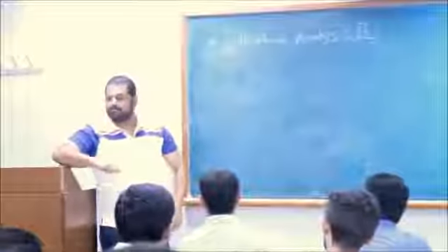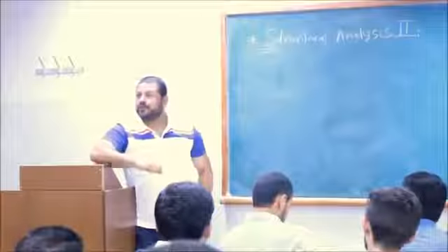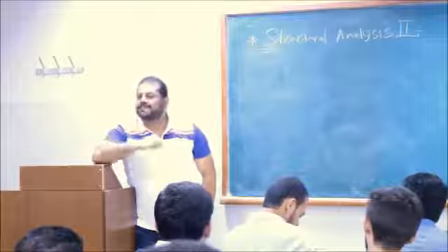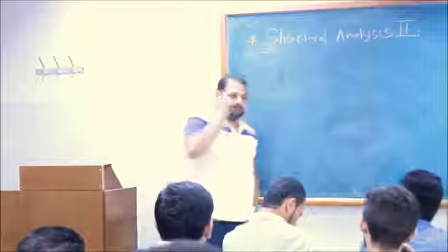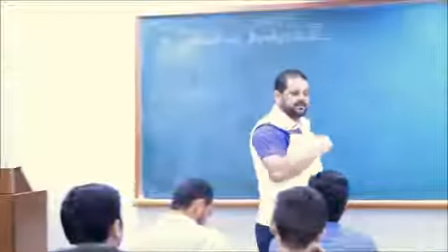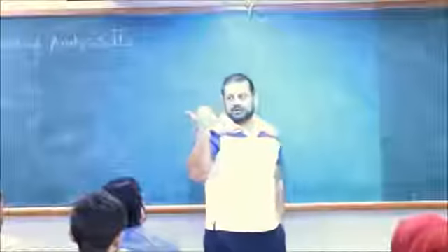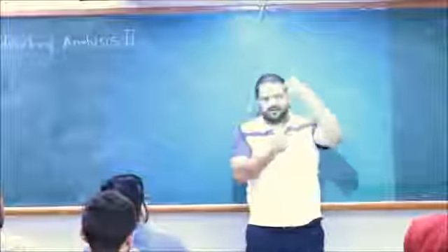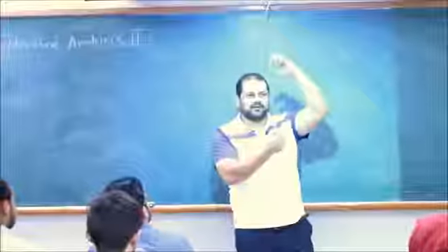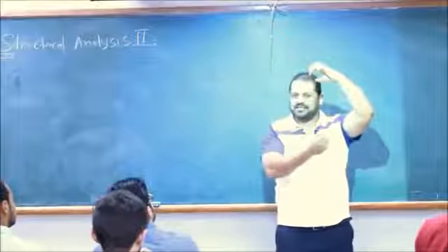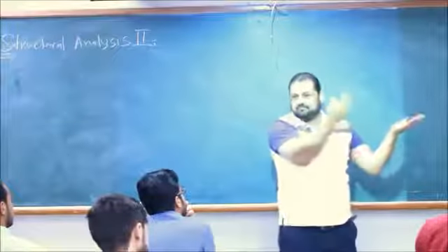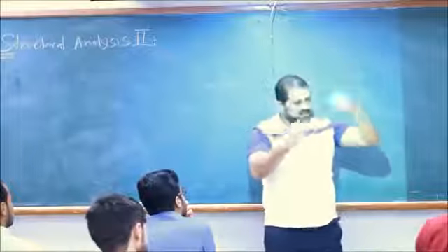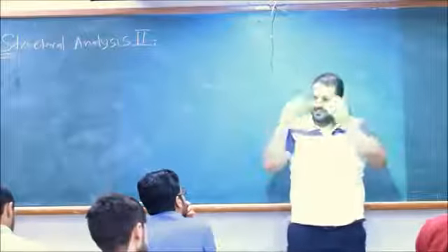Anyway, so do they carry the same load? The steel and concrete, do they carry the same load? Do they have the same deflection or strain? Yes. That's what's called compatibility. Otherwise, you have debonding. Same deflection, compatible. Otherwise, they can have debonding. The concrete will go that much and the steel will stay here. Have you ever seen something like that? That's what we call compatibility. Let's examine it to explain compatibility, so you see it.